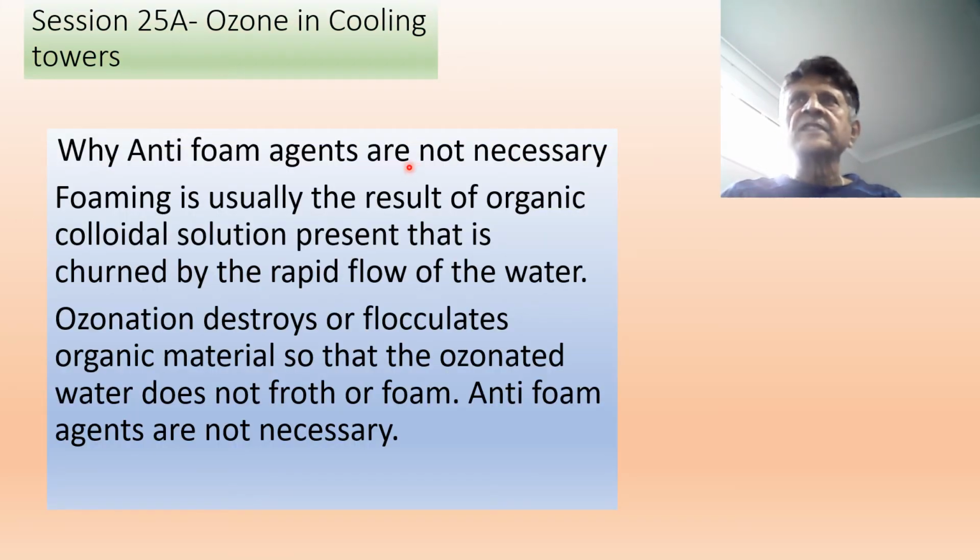Why anti-foam agents are not necessary? Foaming is generally the result of organic colloidal solutions present in the water, and that is churned by the rapid flow of the water. Ozonation destroys or flocculates organic material so that the cooling tower water does not have any organic material that can cause the foam. So there will be no froth or no foam, so anti-foam agents are not required.